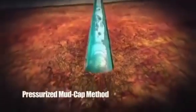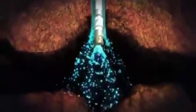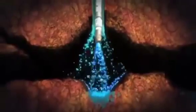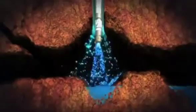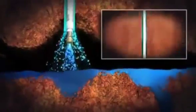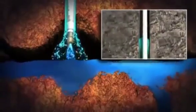In the pressurized mudcap drilling process, a much different response provides a safer, more cost-effective solution. As illustrated in this scenario, as soon as the fractures are encountered and drilling fluid is lost, the well annulus is closed with the RCD. Sacrificial fluid is pumped down the drill pipe, and a fluid cap, often just plain seawater, is injected into the annulus or circulated into place via the casing.